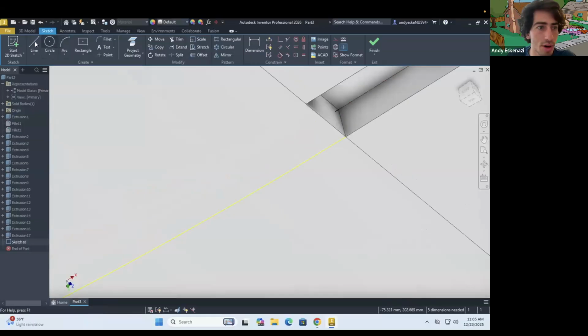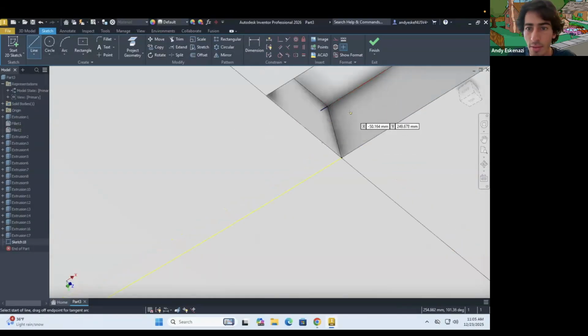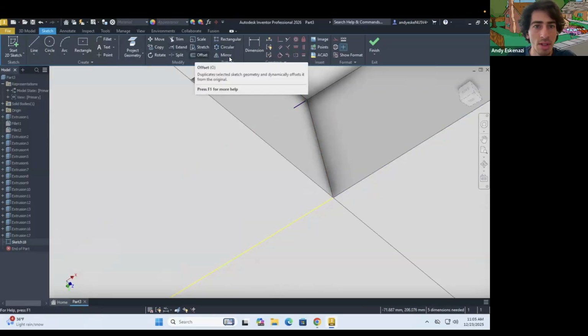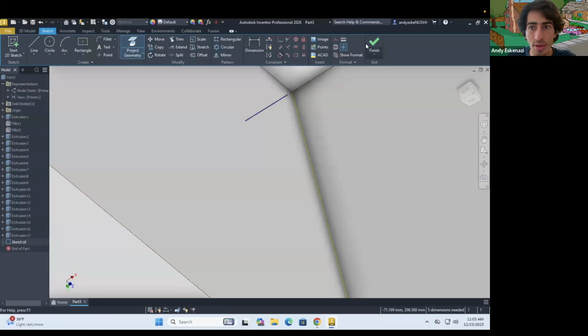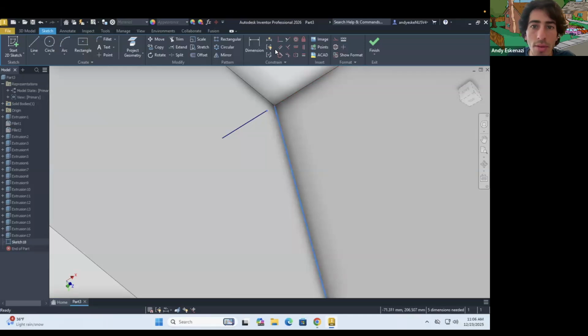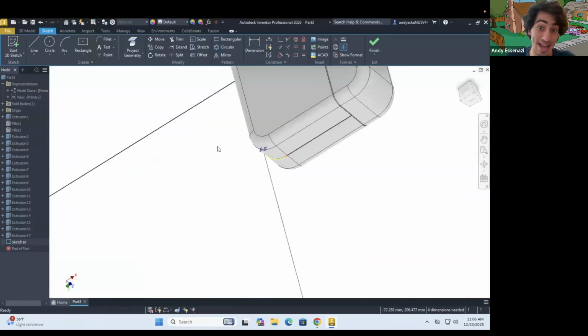We'll see whether this works in just a moment. At least, there we go. Oh, I think we're having the same issue as we were having before. Let me see what happens if I go here to project entities and convert that line. Let's see. I see what's going on. That line, and I want them to be coincident. There we go. I think that might do the trick.